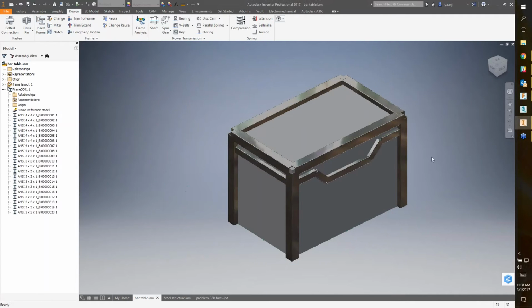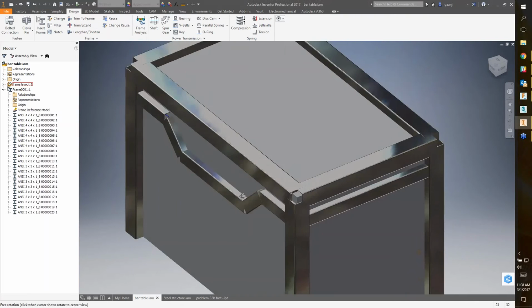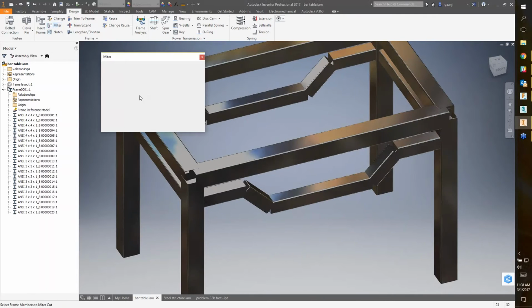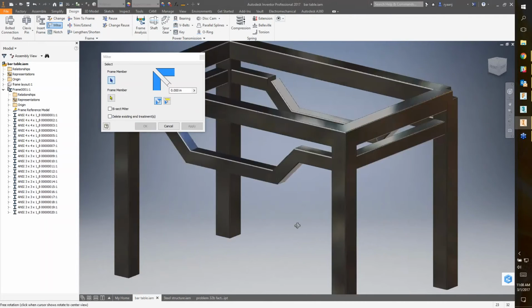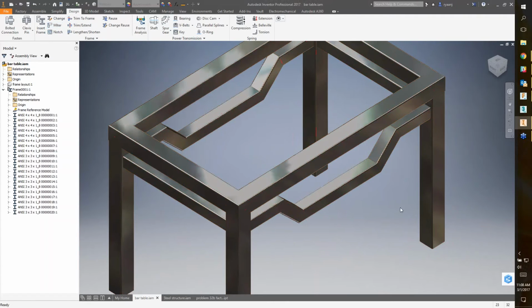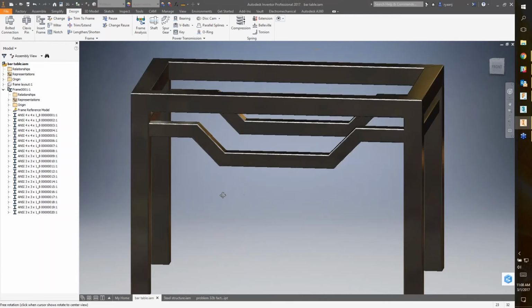All right, so again, this is in Inventor. This tool makes it very easy to design something like this. We've got our layout piece. Let's turn it off. Do some quick mitering on this. Right, so these tools are productivity focused. We basically lay out the design and let Inventor generate the parts for us. Do some quick end treatments and connections. I could continue and trim all these frame pieces off and complete this design, but I don't want to get that deep. We're just kind of looking at an overview here. This is a very quick way to do this.